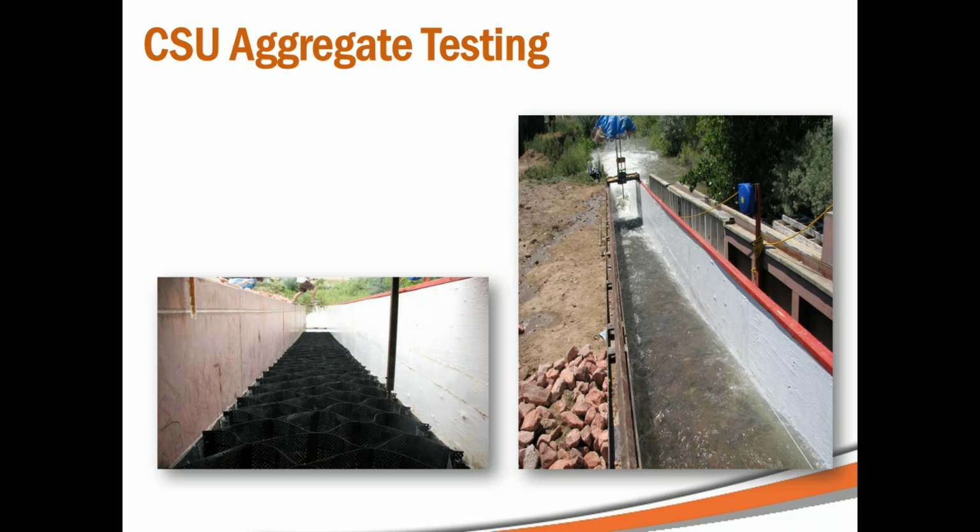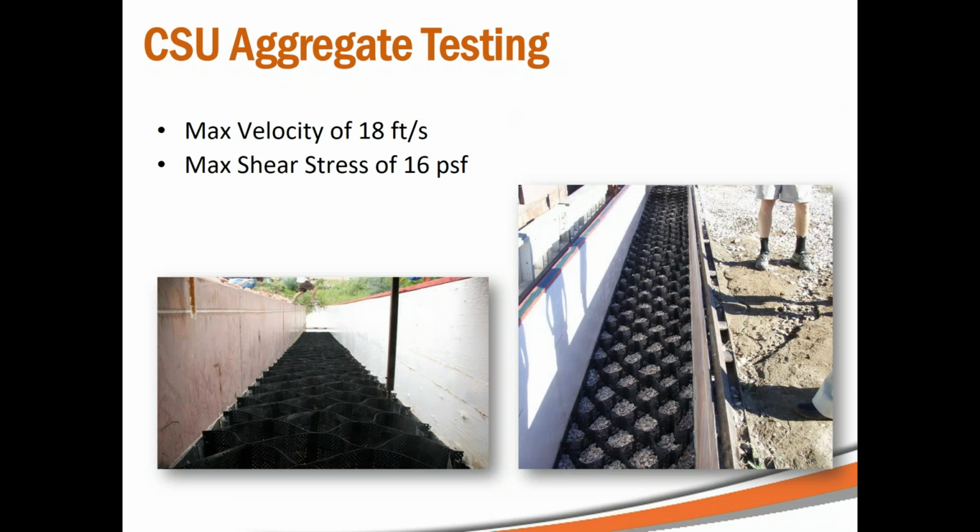Tests were performed with varying water flow and bed slopes, and with 2 different aggregate sizes. A non-woven geotextile was placed underneath the GEOWEB panels, but no surface protection was used. No geosynthetics and no grouting of the stone. We looked at how well the aggregate stayed in place during the test to determine the rock size that would not wash out, so no post-installation maintenance is required for these systems.